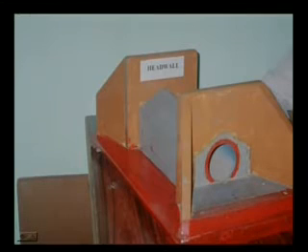This is the other perspective of a pipe culvert, right? You can see this is the downstream side of the pipe culvert. This is the head wall. This is the length of the head wall. This is the other head wall. That means we have two head walls, one on the upstream side, one on the downstream side, and these two head walls hold the pipe in position. This inclined wall here is called the wing wall.